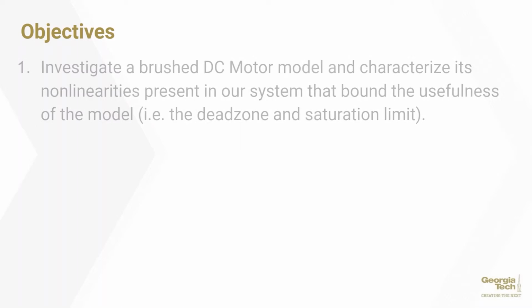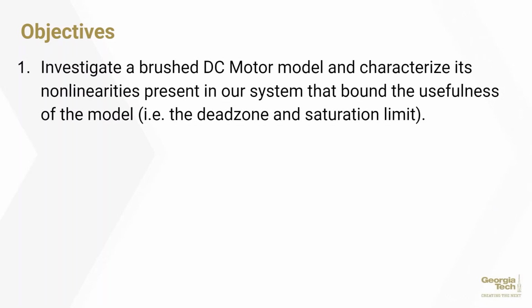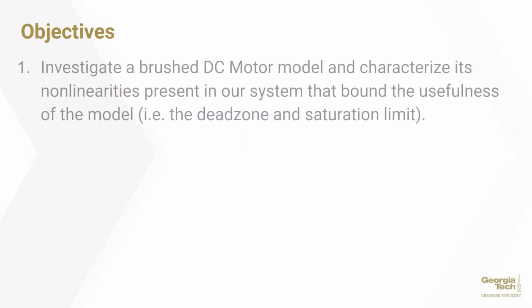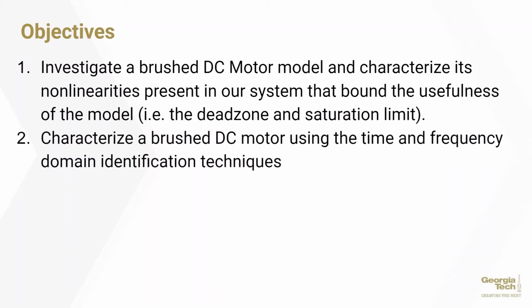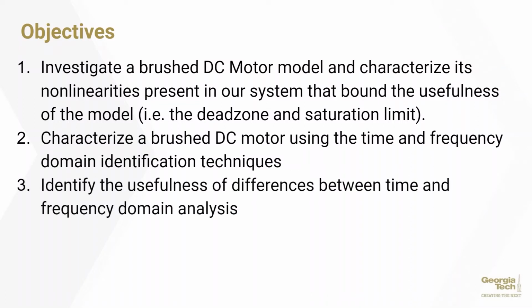Our objectives: 1. To investigate a brush DC motor model and characterize its nonlinearities present in our system that bound the usefulness of the model. 2. Characterize a brush DC motor using the time and frequency domain identification techniques. 3. Identify the usefulness of the differences between time and frequency domain analysis.